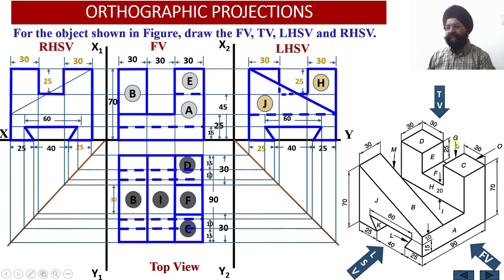Now because the observer is going to look at the solid from this side, a certain portion of this inclined web will be visible to the observer while looking from the other side through this slot. So through this rectangular slot, whatever portion of this web is visible to the observer will be drawn as a dark one, whereas the remaining portion of this inclined web which is covered by this vertical wall over here will be drawn as a dotted surface, right?